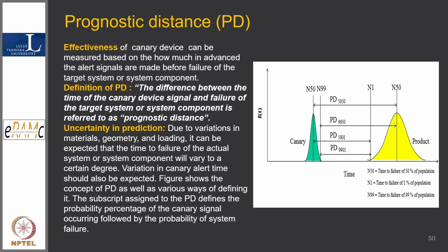They are the first signal for prognostics actually. But one has to be really careful. Only when degradation has genuinely happened should it give a signal; it should not provide any spurious signal. Otherwise, if you design a canary which starts giving spurious signals, and in the plant we have canary based maintenance, or POF based maintenance, or RUL based approach, it will become a problem. So you have to safeguard yourself. The spurious thing should not be there. It should not be too early. It should not be so sensitive. It should give the signal right at the time which is required for maintenance purposes.